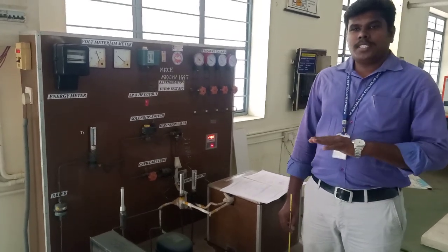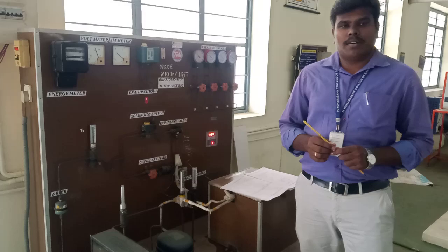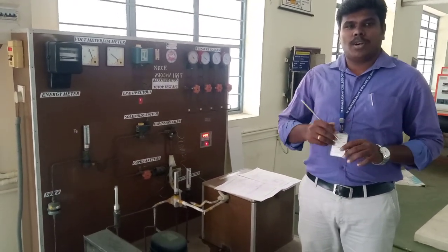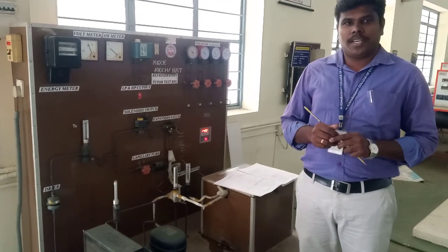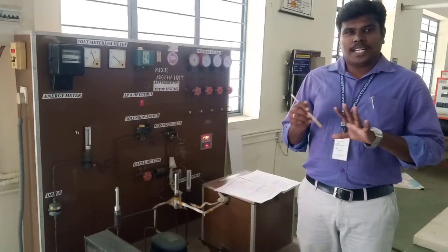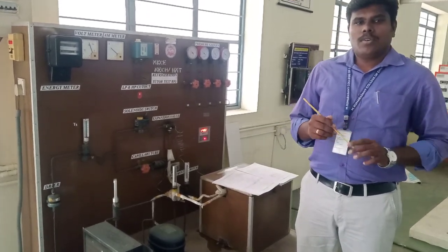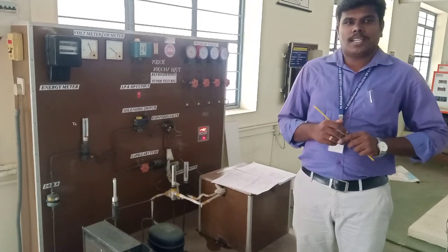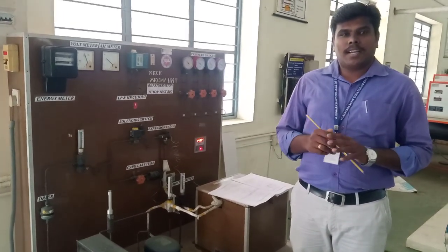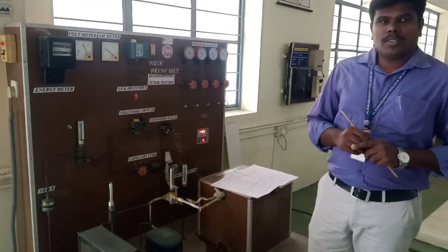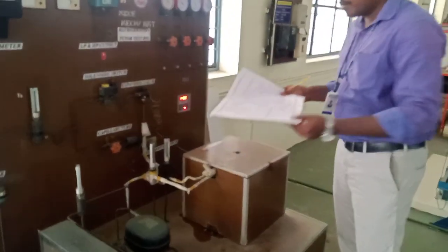Refrigeration basically follows the physics of sensible heat and latent heat. In sensible heat, there is only a change in temperature, no change in phase. But in latent heat, there is no change in temperature, but there will be a change in phase. The law applied to the refrigerator and air conditioning is the second law of thermodynamics, which is the Clausius statement. The refrigerator consists of four major equipments, which are the condenser and then the expansion device,